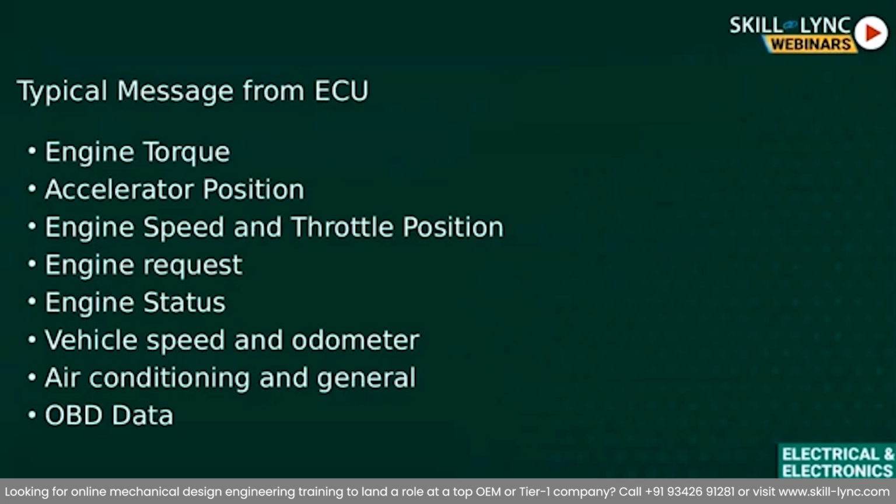And as we are going to talk about automotive electronics, we can't skip embedded systems. For you to integrate all these sensors to a controller, your ECU, electronic control unit, is nothing but a microcontroller inside. So you have to know there are three types of output that you can expect from any sensor. One is analog output, the second is digital output, and the third possibility is PWM or pulse width modulation output.